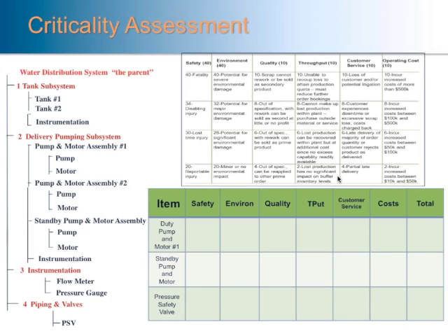A simple example of a water distribution system for the purpose of exploring this further, I've pulled out 3 pieces of equipment from that hierarchy of equipment. We see the duty pump and motor number 1, which is running all the time, along with number 2. And then we have a fully redundant standby pump and motor, which is going to come into service when required if there was a failure of 1 or 2. And then the pressure safety valve.